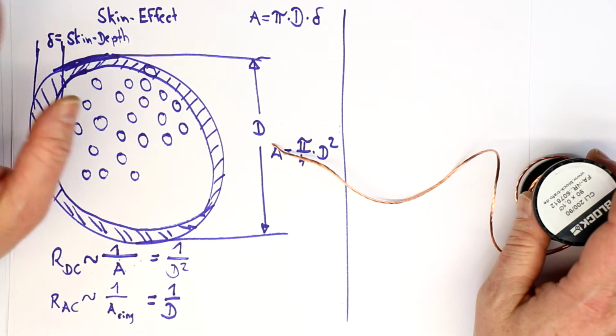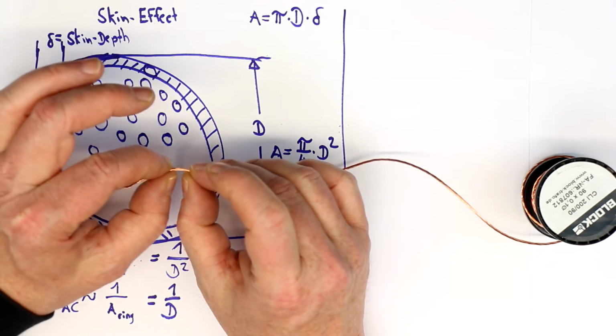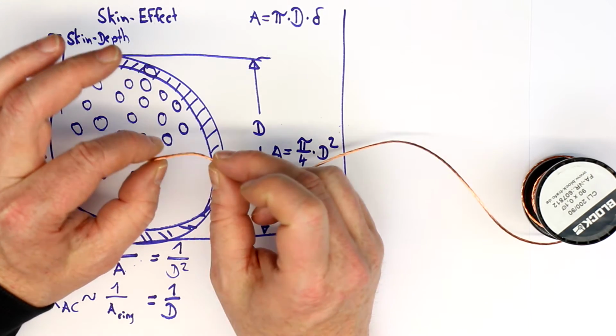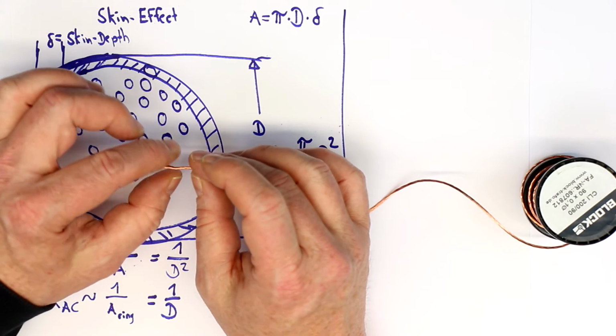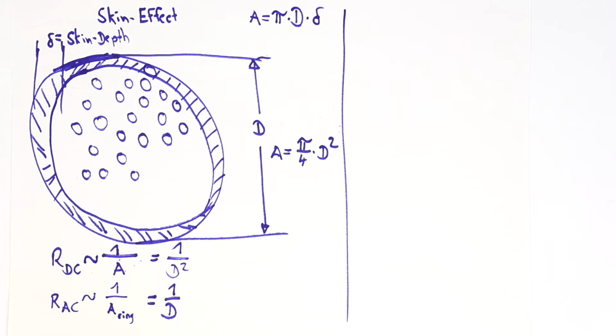I know it's not quite easy to understand. Just remember, it's very important that first of all, not a single wire breaks in your winding, and secondly, that at the end all the wires have to be tinned, not a single one has to be left out.